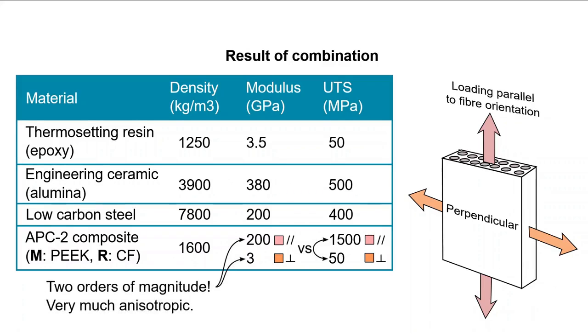If the arrangement is as shown, then parallel to the loading orientation, the composite strategy is realized. However, in the perpendicular direction, it has the same properties as the matrix. Clearly, this highlights the level of anisotropy which could be characteristic of fiber-reinforced composites.